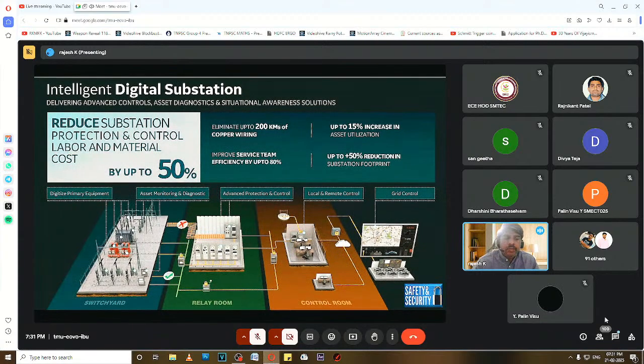So that's all at high voltage. You need to step down to a value which you can comfortably work with, and you can monitor, you can filter the components, you can monitor the harmonics. So for all these things, you need to scale down. So these current transformers and the voltage transformers will be digitized.